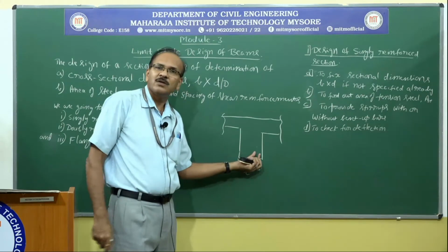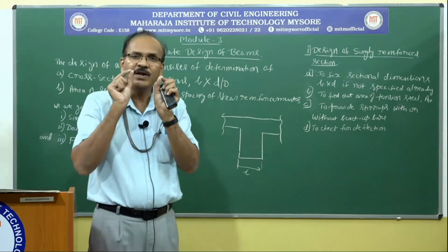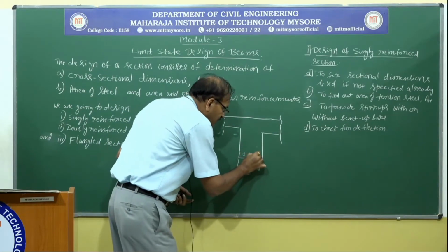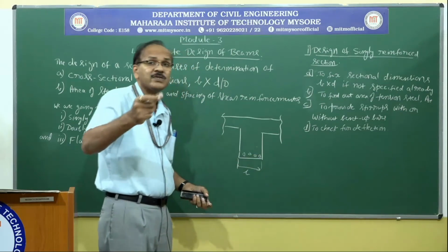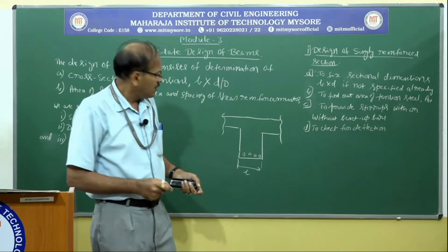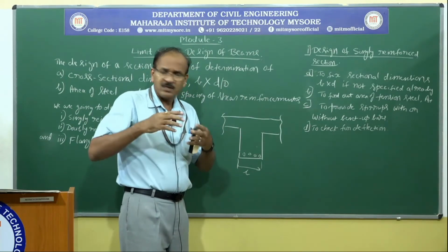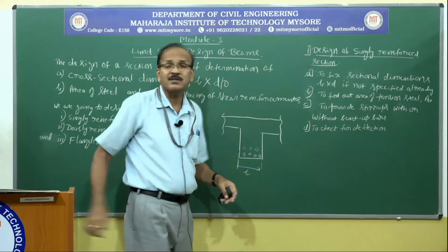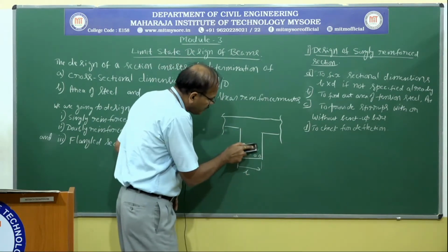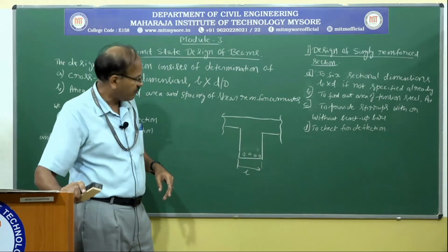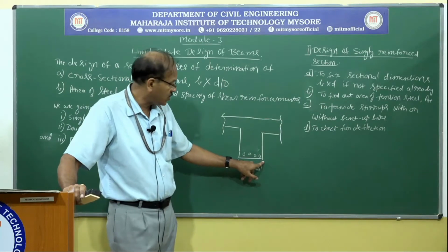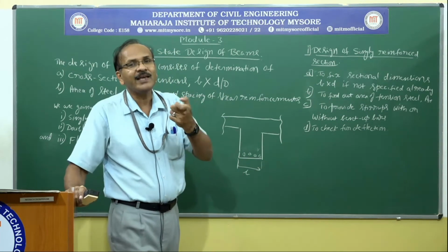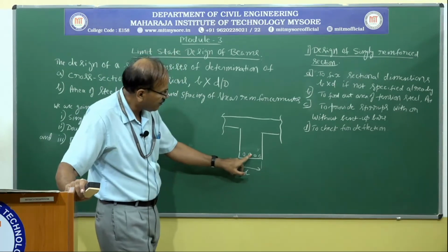If we have reinforcement, we have to maintain certain spacing between reinforcements as per the codal recommendation, and also provide vertical spacing and horizontal spacing. Horizontal spacing is the side spacing. If the beams are heavy and the span is too much, in such cases we go for 2 layers of reinforcement. But you don't have to worry about 2 layers; we are going to worry about only 1 layer. So when fixing the beam, we have to make sure the reinforcement is accommodated within the width without violating any codal provision on the spacing between individual bars and also the side spacing.